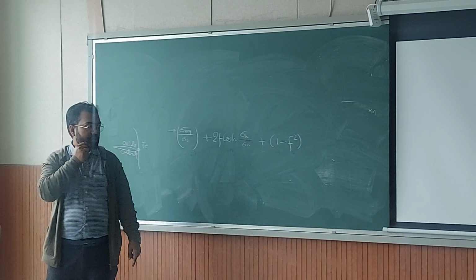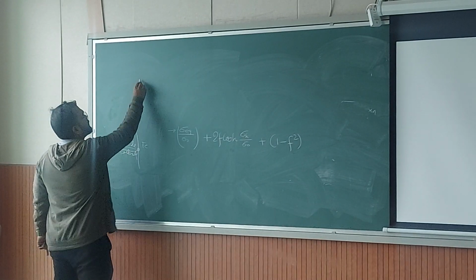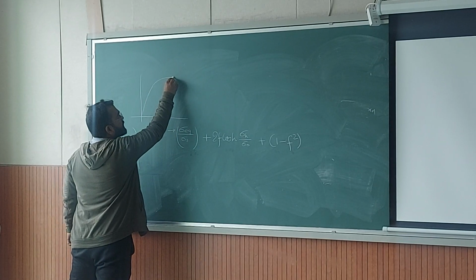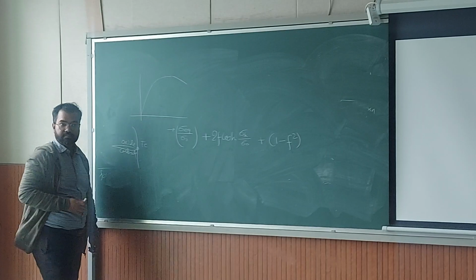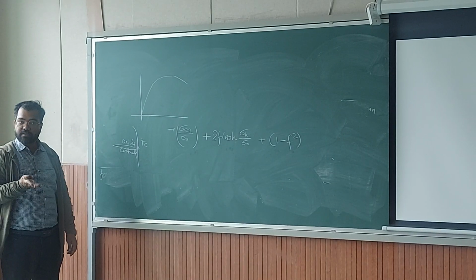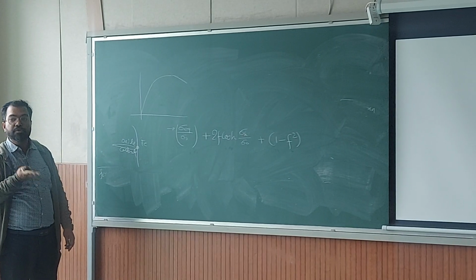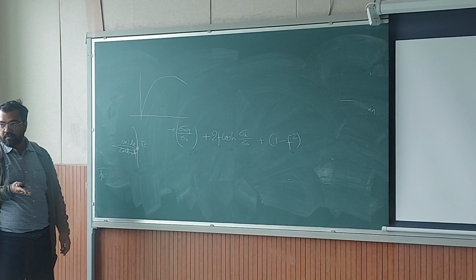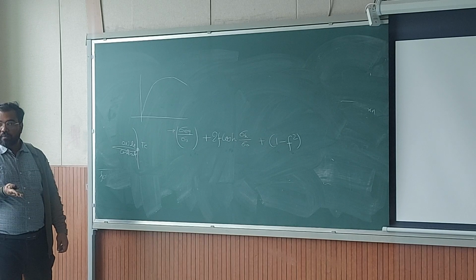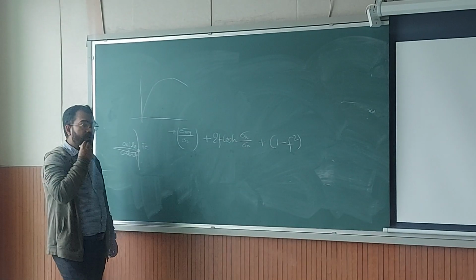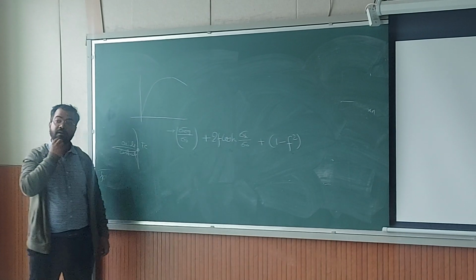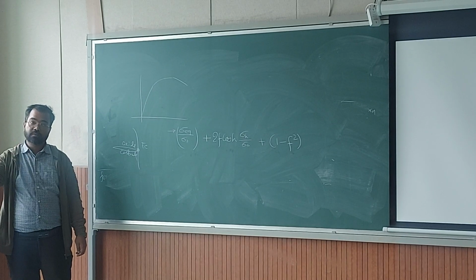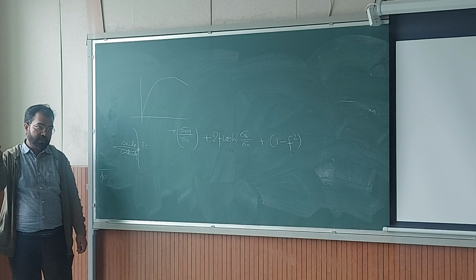And in this case, apart from hardening, the curve will go down. So you can also simulate softening because the new yield points are lower than the previous one. Okay? So this could be another way of defining yield point in comparison to what we had, the von Mises criteria.